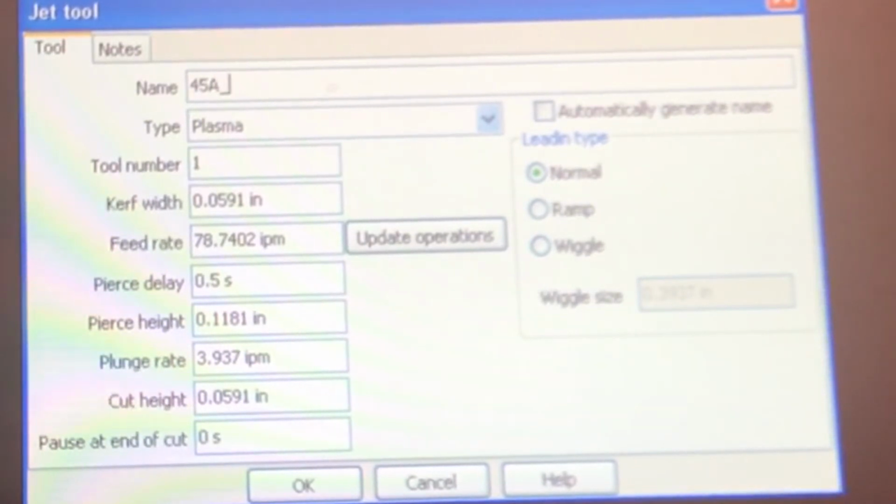We'll do an underscore, and this is more just a separation so you can stay organized and reference this. Then I call out the thickness of material. We cut a lot of 16 gauge, so we'll reference off of that. If it's like 1/4 inch, just put 1/4, and that's just the thickness of the material you're cutting. Then we give another space with an underscore. Then I call out the type of material, which typically we run mild steel. But if you're running aluminum or stainless, I would adjust that to AL or ST, but you can change that to however you like.